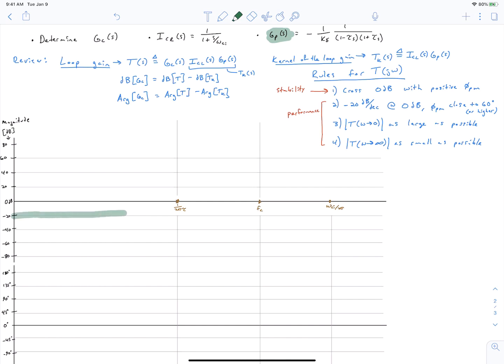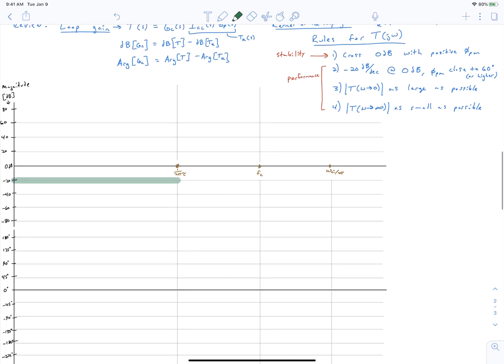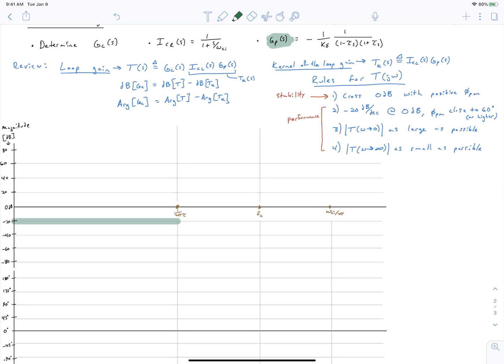And so we do this using our typical Bode plot techniques. And you can see we're going to be at this constant gain up to the frequency of 1 over tau radians per second. So if we convert that to hertz, we divide it by 2 pi. And then at that point, we hit 2 poles. And so we're going to start decaying at 40 decibels per decade.